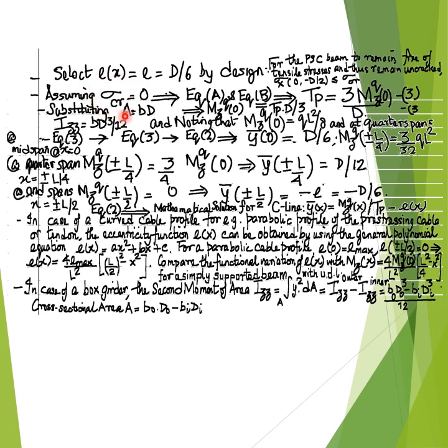Thus, assuming the cracking stress or the cracking strength sigma subscript CR of concrete equal to 0, signifying that the limiting condition that is specified by equation A will result in a pre-stressed concrete beam that is entirely in a state of compression or free from tensile stresses,